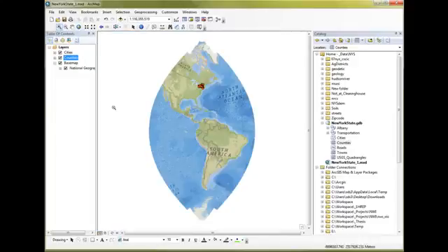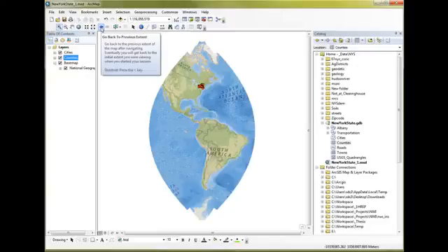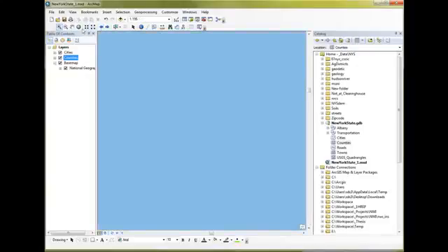What you're seeing is another feature of ArcGIS 10, and that is something called a base map. I have added a base map to my normal data sets to give a little bit of background information, a little bit of context. I grabbed this base map right from the web, and I'll show you later how to do that. But when I went to the full extent, of course, it included the base map. So that's not really where I want to be right now. So instead I'll hit go back to previous zoom, and I will use another option.